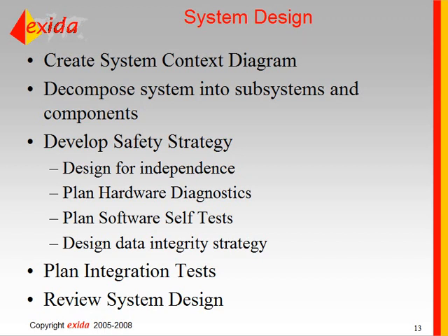You can then break your system into safety critical parts and interference free parts. Essentially, the interference-free parts do not have to follow all of the requirements of 61508 in your development. So you could potentially reduce the overall amount of development work and overhead that's introduced by the standard by coming up with a strategy for showing independence between components.